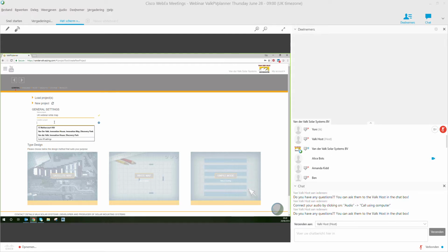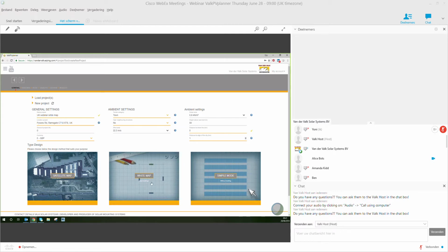Do that now. You still have to put in a location, because although you can't see the building on Google Earth if it's new, you still need to know the wind speed, the height above sea level. All of that is determined in this section where you're putting in the location. Okay, use that address. Maybe this time it's town. Still no height. Surrounding structures. Distance to the shoreline might be only 5 kilometers. Distance to the edge of the city might be 1. So just 1 kilometer inside the urban area.